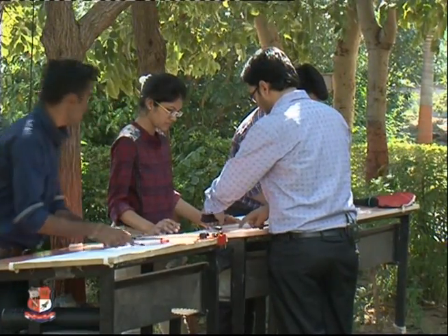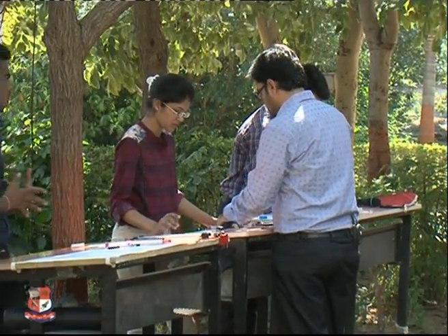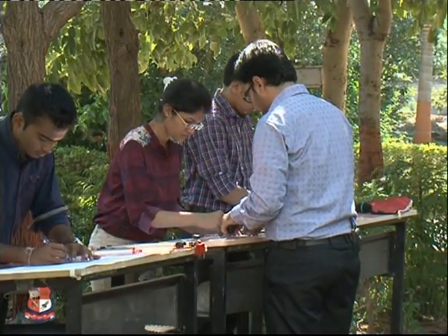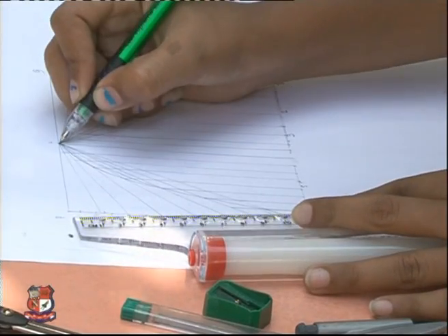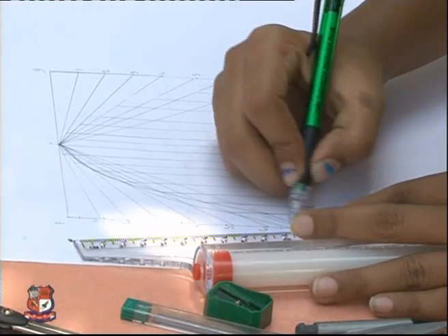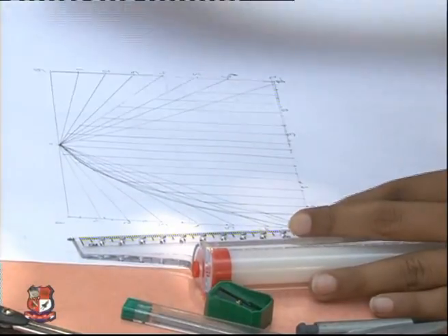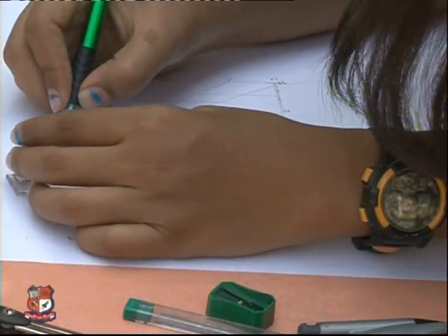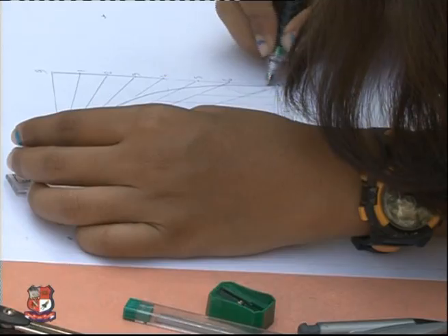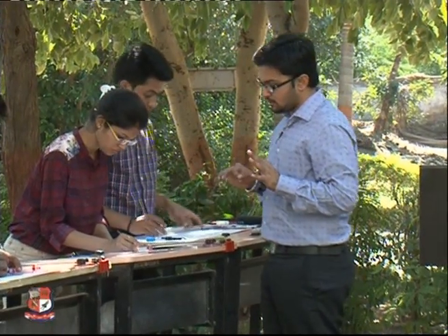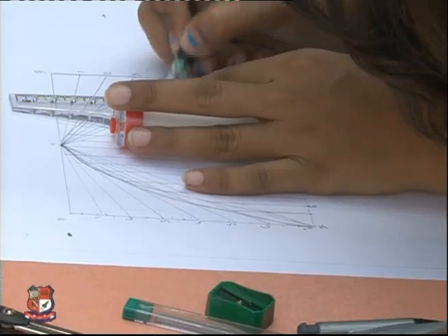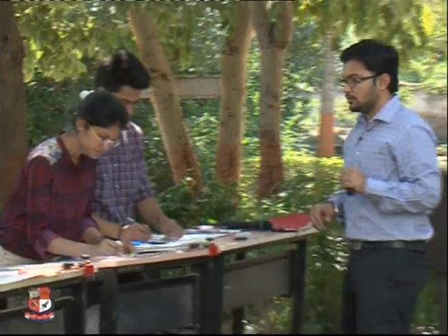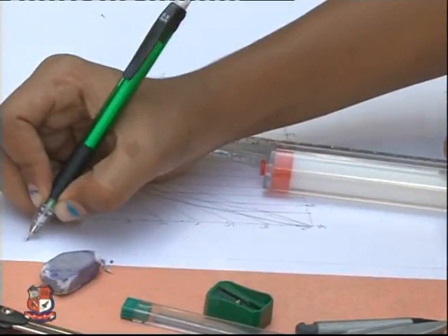Now here, whenever you are drawing this, you have to show the measurements of it. What is this measurement? You have to mark it from here. No engineering drawing is finished without writing the measurement. Horizontal lines from here, and similarly the same will go for the vertical lines. So this is what a complete parabola looks like. Mention the unit as centimeters. So that is a complete solution.